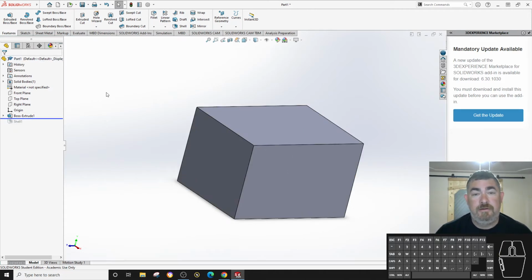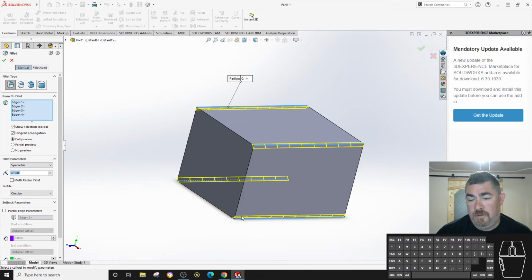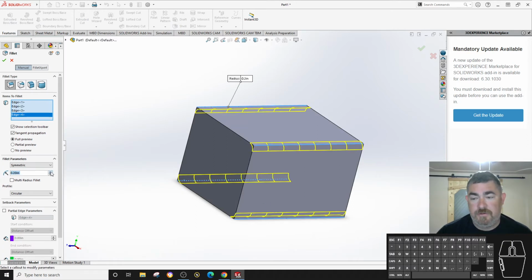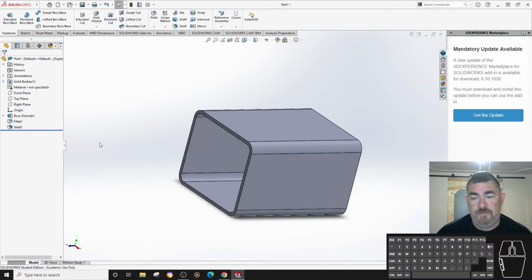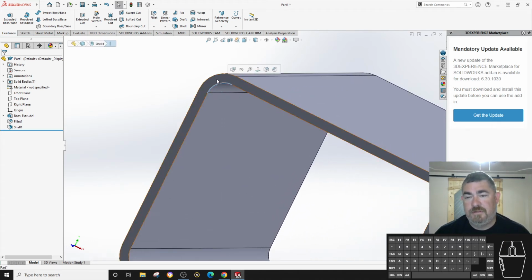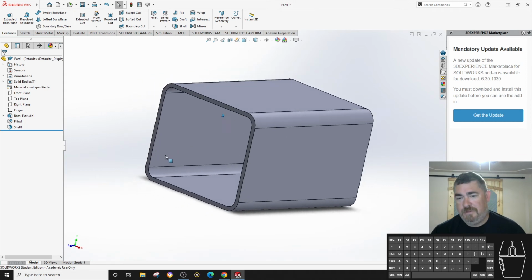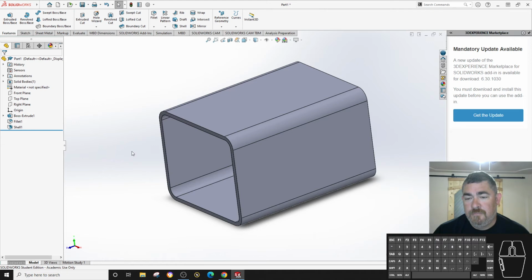So if I go above that, kind of go back in history and add a fillet to these corners, at least to make it bigger than the shell thickness. Now when I do the shell, it's automatically going to come in and have that radius here. And so this radius is going to be whatever the thickness is less than this radius. So there I've got a piece of rectangle tubing that I can make however long I want using the shell command. Real easy way to do it.